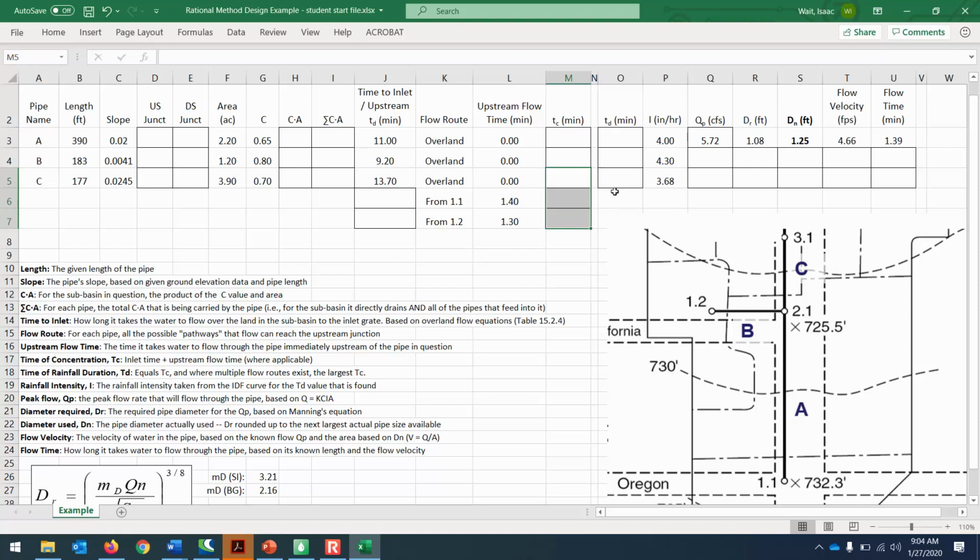The reason for that is that the worst case scenario for peak flow is when all of the area in a watershed is contributing at once. If this parking lot, just as an example, takes 10 minutes for all of the water to travel to that point from all of the contributing areas within that watershed, that 10 minutes is going to have a higher peak runoff than how much area is contributing during a 1-minute event.